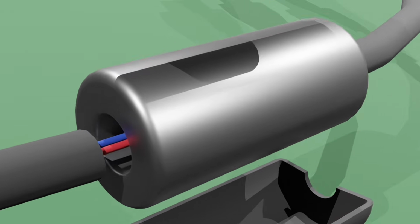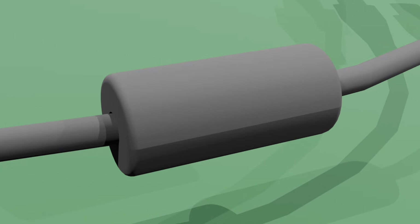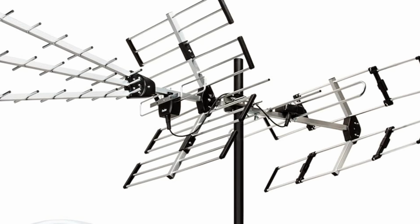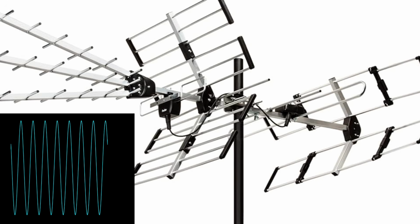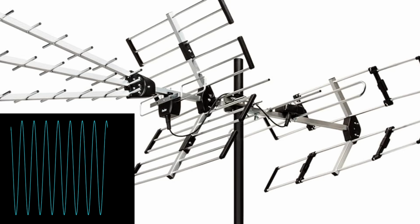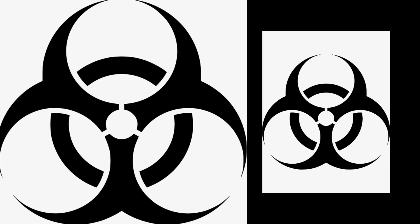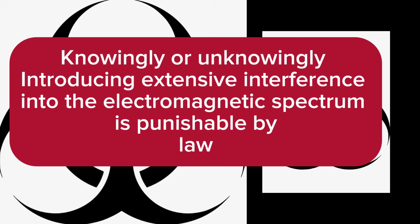Without this bead, the cable would work like an antenna, broadcasting all high frequency noise from the power stage into your house. This would affect your Bluetooth and Wi-Fi like EMP. I won't go deep into EMP because some of you might be planning bad things. So what it does is that it suppresses the high frequency noise that might have proceeded to your PC.